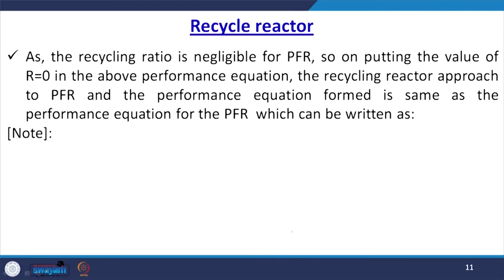Now, sometimes we see that the recycle ratio is negligible for PFR, so on putting the value of R, that is the recycle ratio, equal to 0 in the performance equation which we discussed, the recycling reactor approaches PFR and the performance equation becomes the same as the performance equation for the PFR.